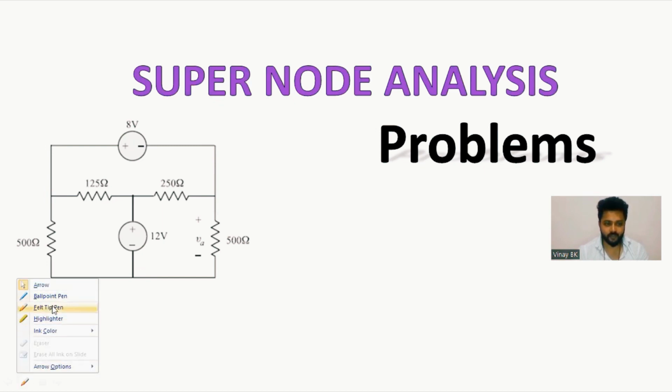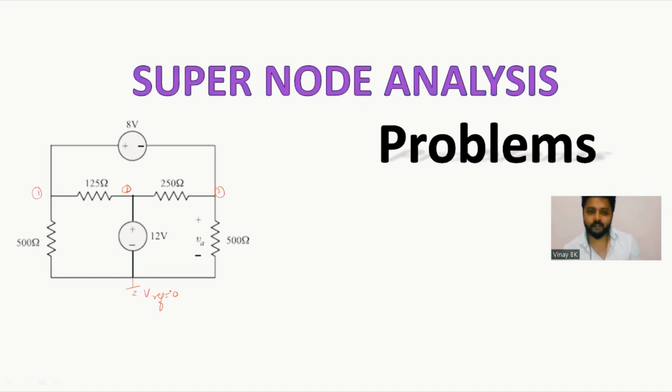Here, the supernode is nothing but this. How many major nodes are there? One, two, three major nodes and one reference node, that is V reference, the value of which is 0. Now the voltage source which is between two major nodes, major nodes 1 and 3, so you can call V1 and V3 the supernodes with respect to 8 volts. So that you can write the equations of V1 and V3.